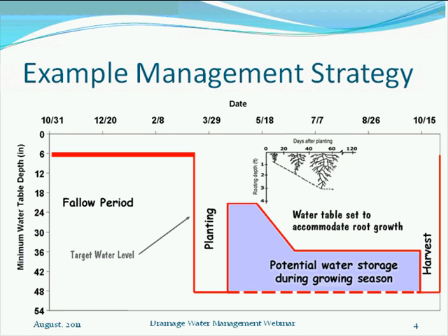Okay, then you're going to harvest your crops. Once you harvest your crops, then it's time to put your flashboards back in and bring that water table back up in the field. Another thing to remember is that if there's going to be manure applications on this field, the practice standard does require you to use the drainage water management infrastructure to make sure that you raise the flashboards before and during manure application. And that's going to help prevent loss of those nutrients through the system.